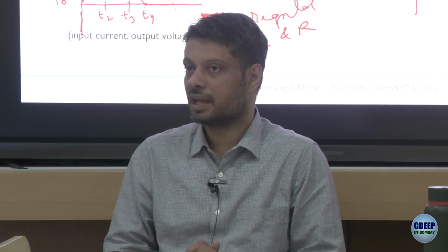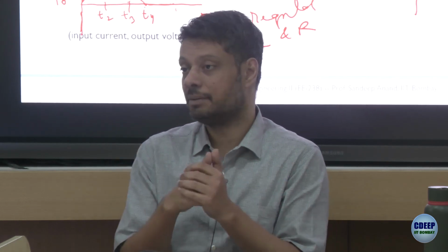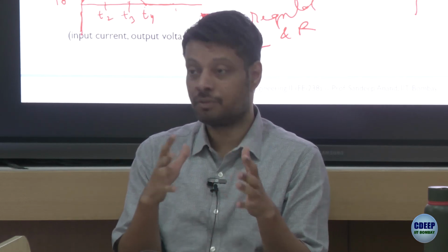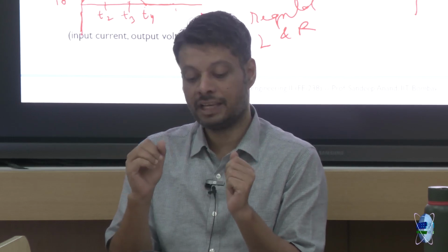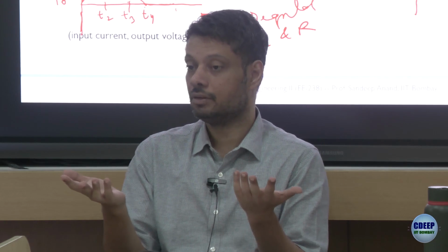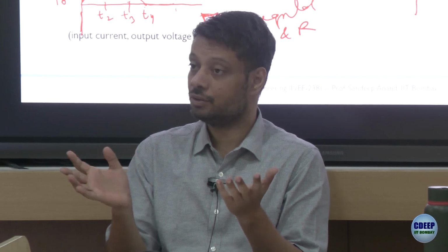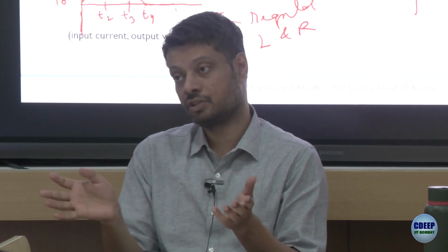What happens at T4? The current is 0. So if current is 0, again let's apply the same thing, right? Now, whether the diode will conduct or not. Hypothetically, let's assume the diode will not conduct. So di/dt is 0. Current in the resistance is 0 anyways, so I into R is also 0.